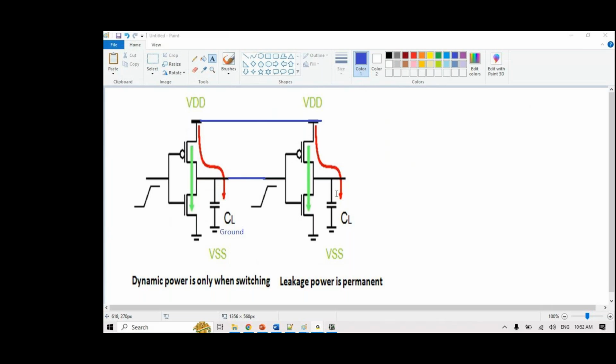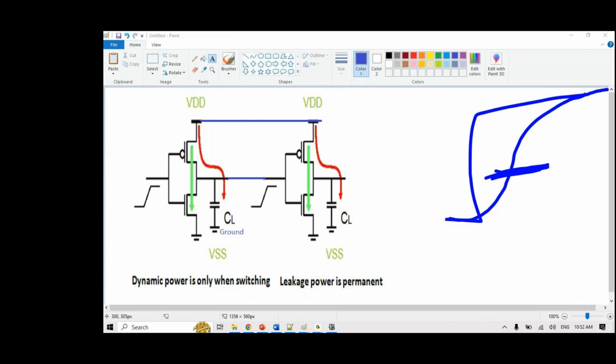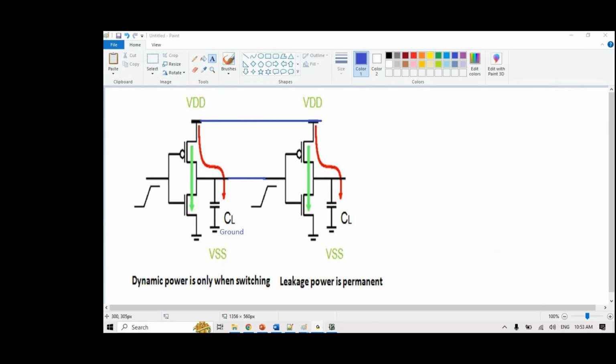Now take the opposite side, where the threshold voltage is high. It will take a lot of time to turn them on, because this capacitor needs to charge for a much longer duration. Only then you will see that voltage difference. A capacitor doesn't go from 0 to 1 immediately like this. It goes like this. So this is where the low VT transistors will turn on, and this is where high VT will turn on. This is the timing difference. Here the switching speed is very high, while here it takes so much time to switch the transistors. So that's the relation.